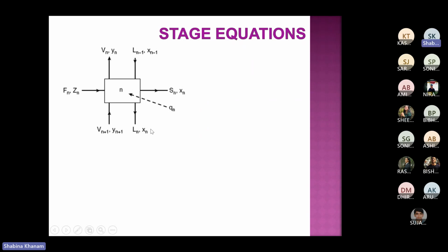Now, what about this nomenclature? How can you understand it? The easiest way is to identify from where, please listen carefully, from which tray the stream is exiting. The nomenclature is based on that tray, from which the stream is exiting, not entering.